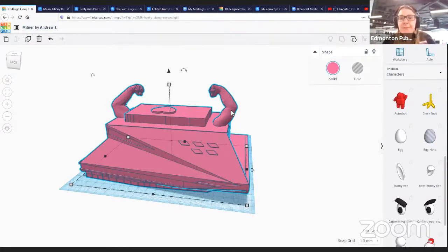So this object could be thousands and thousands of lines of code if we were to send it into the program that's called the slicer. That's what Jermaine was showing us earlier. It takes the dimensionality from the STL and derives instructions based on both the machine settings and the software specifications as well.